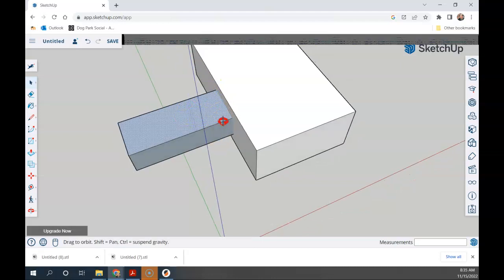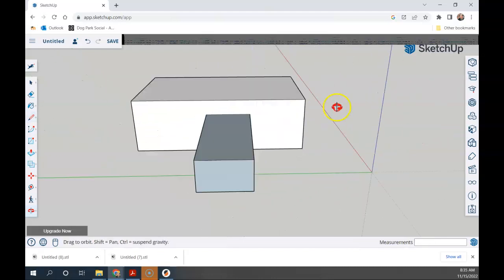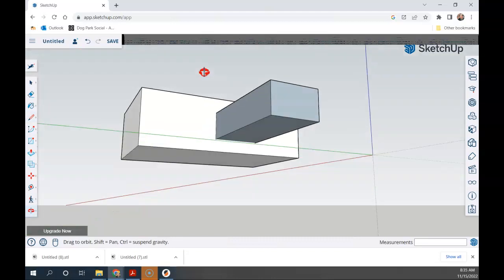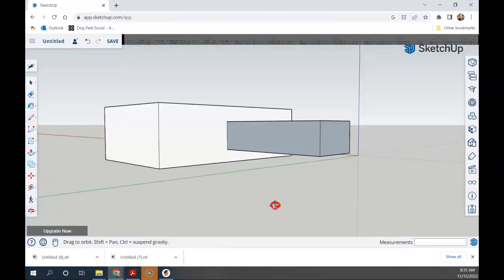So be very mindful of testing out and looking at your 3D print before you do it. If it's not working out, you're going to have to go back and change some of the geometry. In this case, I would probably need to make some lines here to actually form this and have an exterior side, so that this could be joined together.